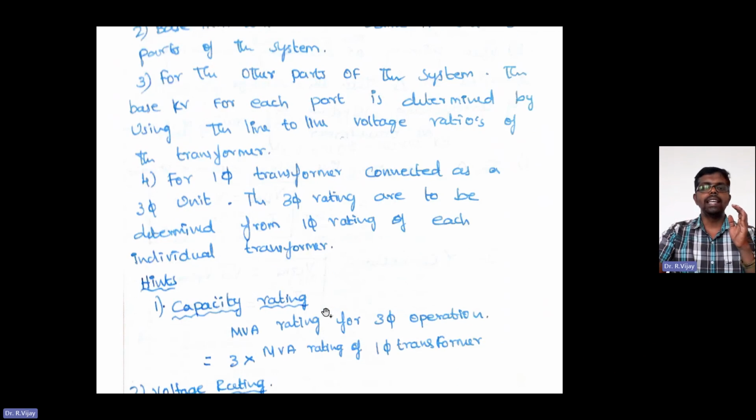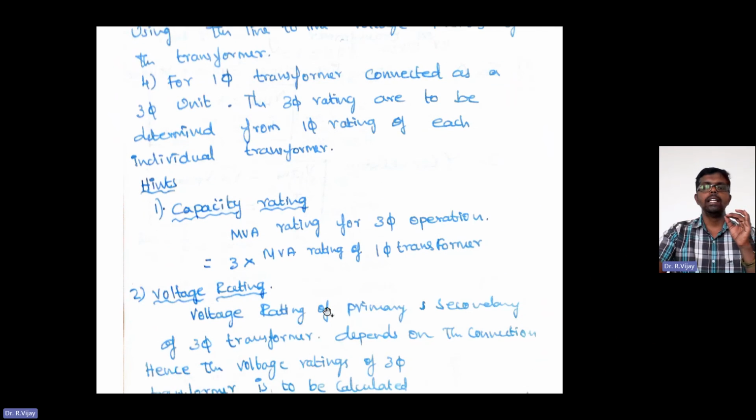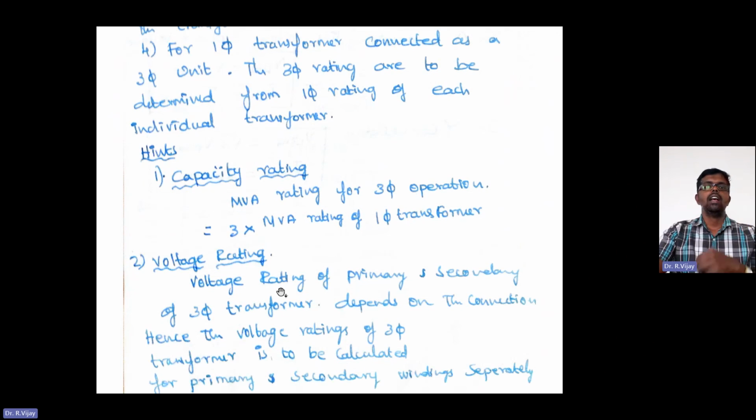Next, some of the hints that you also need to remember for calculating this. What are the hints? Capacity rating. Capacity rating is nothing but the MVA rating of three-phase operation, that is, 3 into the MVA rating of a single-phase transformer. Okay, this is for three-phase.